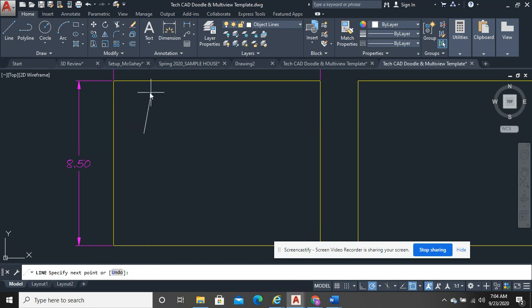That's your polar setting that you set up in AutoCAD, or in Object Snaps. And what that does is it locks you, once it gets you into that green, into a line parallel with that x-axis or parallel with that y-axis.